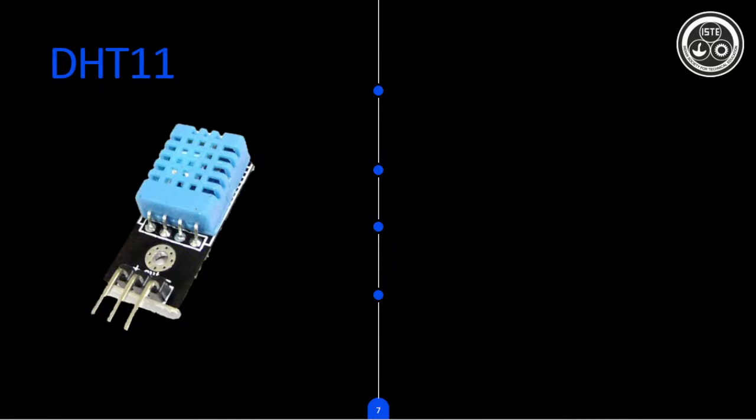This is a digital sensor. First of all, we should know this is not an analog sensor. This is a digital sensor. So what is the difference between a digital sensor and an analog sensor? An analog sensor will give you values continuously. Say, if we are powering the sensor with 0 to 5 volts, an analog sensor can give you values like 0.3 volts or 1.3 volts or 1.7 volts or 4.8 volts or 4.8567 volts, anything, those kinds of analog signals.